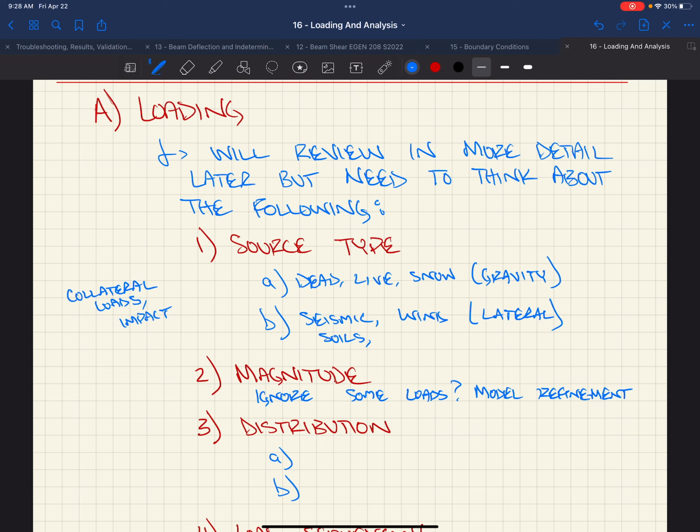So you would want to look at, okay, when I design it for moment, I'm going to look at the worst load combination for the worst moment. And whatever the shear is at that point, I don't care, because I have a maximum one in some other load combination that I'm going to design that beam for. And it's automatically going to be okay. Does that make sense?